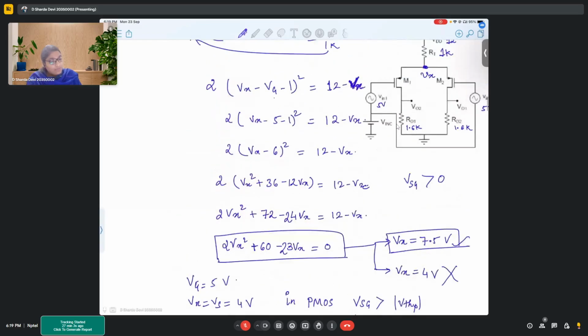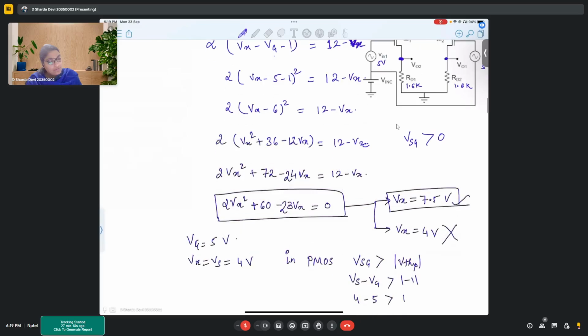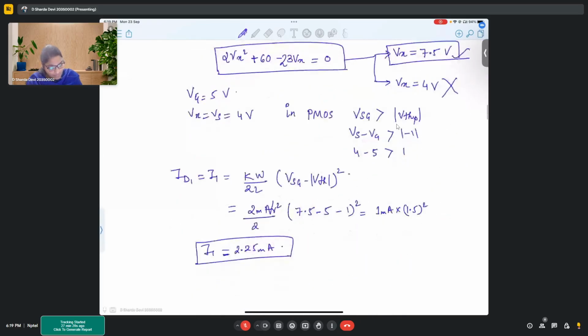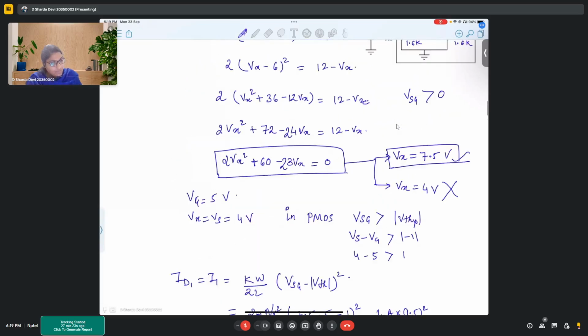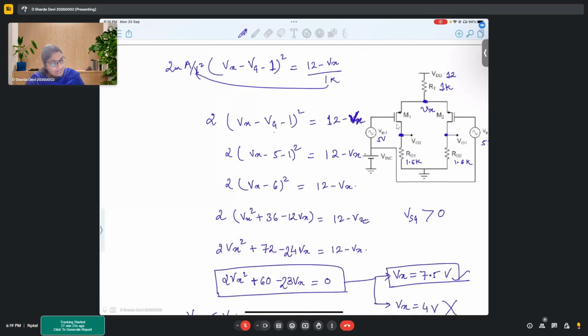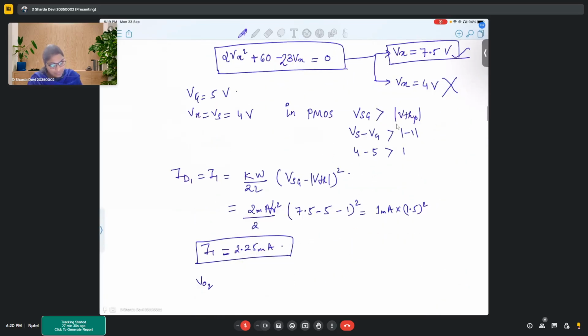Now we have to find this value, right? We have to find the output potential because across this potential only you will have a swing. So to find this V out, V naught 2, if we observe V naught 2, we can see that whatever is the drop across RD1, that will appear as V naught 2, correct? So V naught 2 is I1 into RD1.